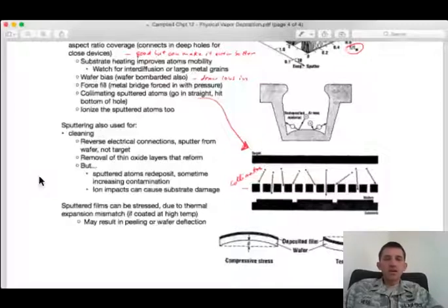If I have a plasma process, I have the inherent participation of electric fields. And so I could bias the wafer to provide that electromagnetic attraction that would actually draw those ions into these high aspect ratio features.